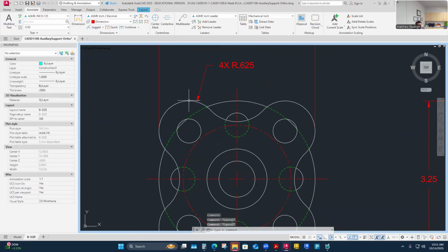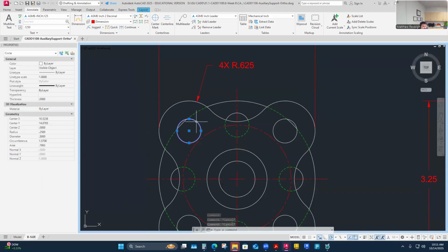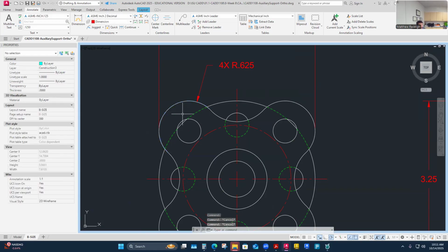So what are my dimensions I have to locate? Usually they're an X and Y dimension to locate it, maybe. Or a circle pattern. Sorry, I'm looking at this feature, not that circle, this feature. Or that circle pattern. I could use kind of the bolt circle concept and tell everyone what the circle pattern is for this hole. I think that's what I'll do for a location. I'll first put in